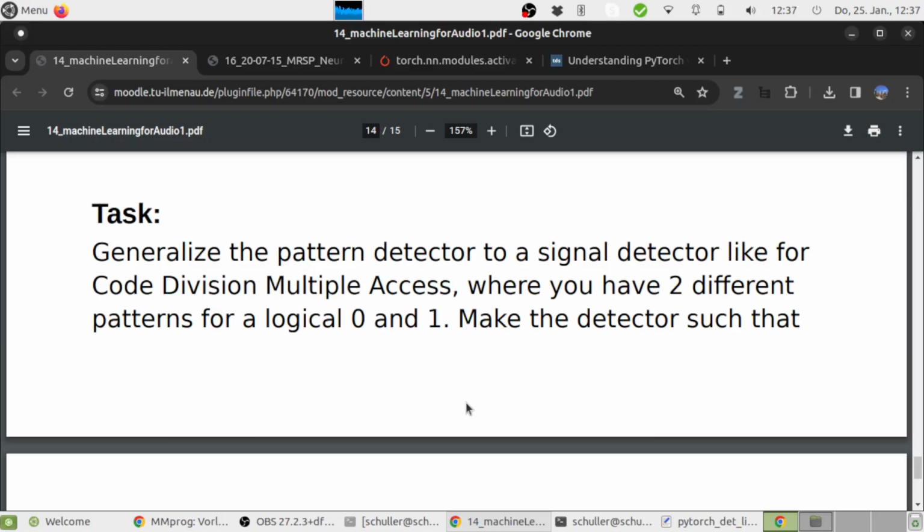And usually you do it in such a way that each transmitter gets its own pattern pair, and in such a way that each pattern pair is almost orthogonal to other stations' pattern pairs, so that the detectors don't get any output from those other pattern pairs. Right. So again, you have patterns where you want the output of your detector to be 0. And that's actually difficult to optimize.